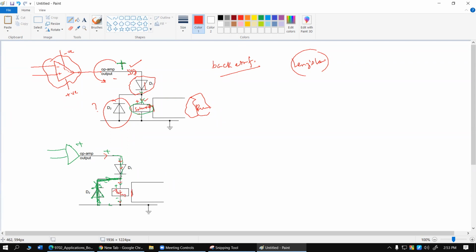It makes sure of this so that the current cannot pass through this left path. But whenever the back EMF is produced, it will allow the high current to flow through this path very well, and eventually this will automatically be managed within the small circuit that we see over here, and the op amp device over here can be protected from potential damage. So this is why we need both of these diodes, D1 and D2, in place. D1 is required to determine what kind of output should energize our solenoid.